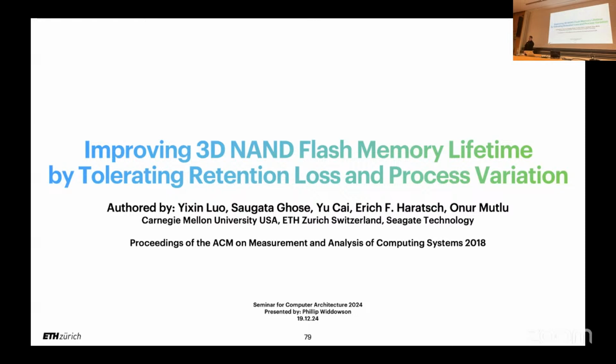There were some questions earlier, like, does this increase the read disturb errors if you do in-place refresh? Yes, it does. So in the paper, we propose that until you get to a point where you cannot recover those errors with ECC, you do in-place refresh, and then you switch to remapping-based refresh.